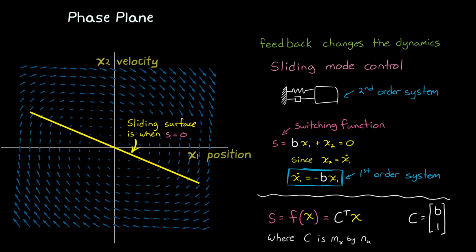Okay, so we now have our sliding surface, and the first job of the controller should be to keep the states on that line. That's priority number 1. However, obviously the system could physically be in any state at any time. There's no guarantee that the system states are initialized along this surface. Therefore, the controller has a second job. It has to make sure that the system can reach the sliding surface.